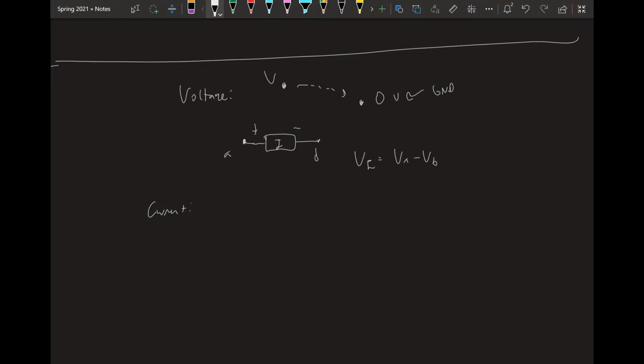Current. We all know what current is, right? It's a charge flow. Current is directional, right? So we'll denote it with a vector. And current can be defined going any way. But when you talk about current, you define it as going one way. If you get the current equals some negative number, that just means it's really going the other way from its definition, right? So if let's say I, in this case, as defined, was negative 4 amps, I could define I as being positive 4 amps going this way. It all depends on, once again, the relative definition of what you've put down.